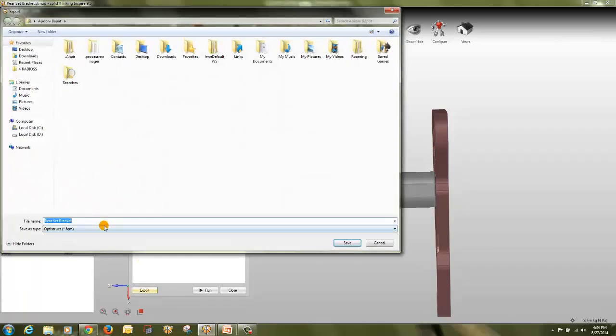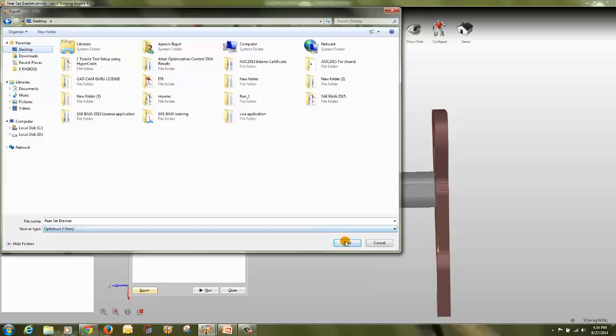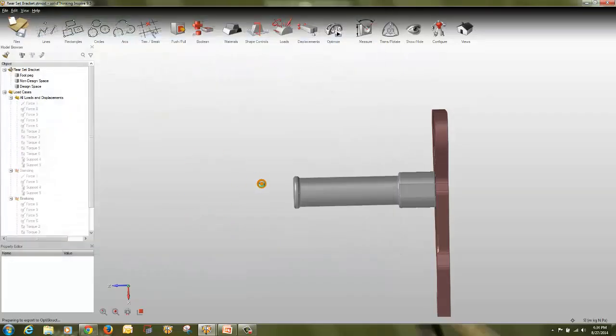You can export the file to FEM. This will help you to solve in HyperMesh. So this will help you to prepare and export to OptiStruct. This way you can create an FEM file of this model and export it, and then open it in HyperMesh. You can import it in HyperMesh after its export.